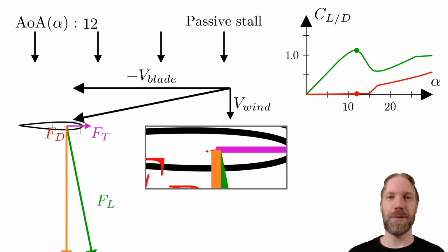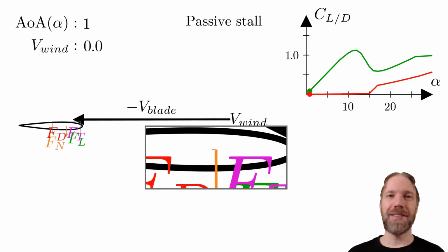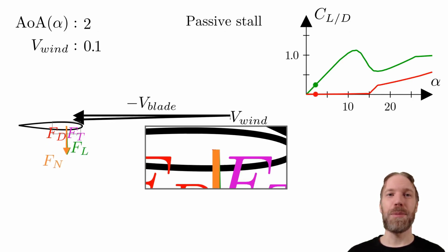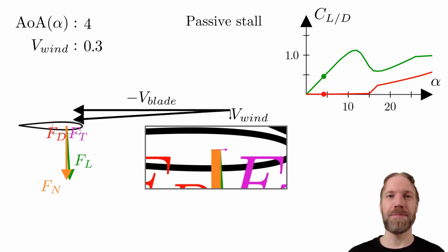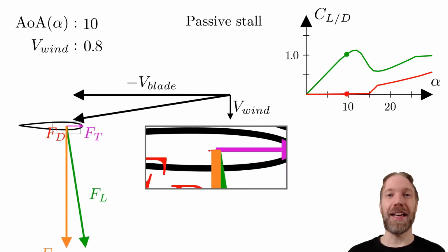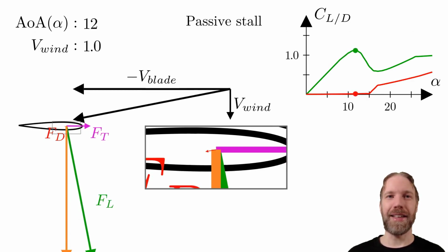We start from 0 wind speed. As we let the wind speed increase to the rated speed, which is 1 here, note that the lift force increases approximately linearly with the wind speed. This will give a quadratic increase in the tangential force as the angle of relative wind also increases linearly. Hence, sin phi gives another linear contribution.